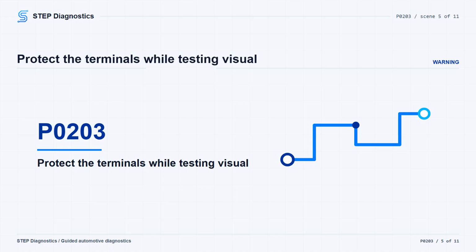Check male to female terminal fit with the mating pin and feel for normal separation force. If the connector shell, pin guide, or retainer is adding drag, remove what is needed to check the terminal fit correctly. If connector bodies, pins, or terminals are damaged, replace the damaged connector pieces.